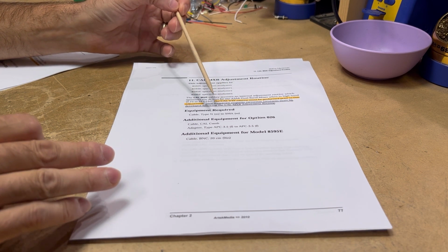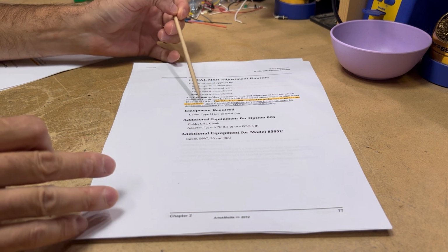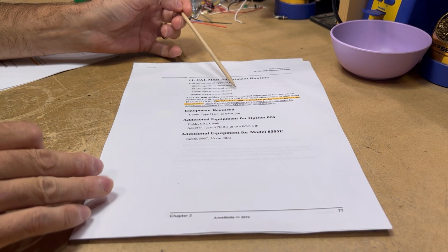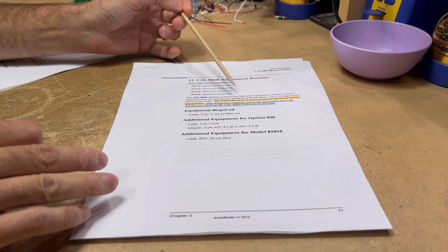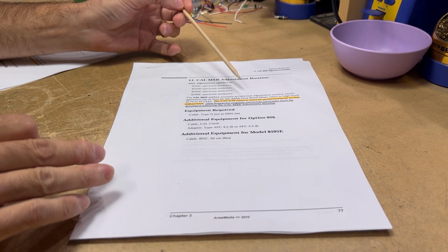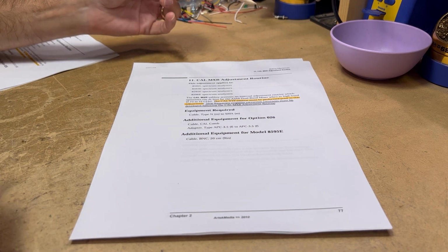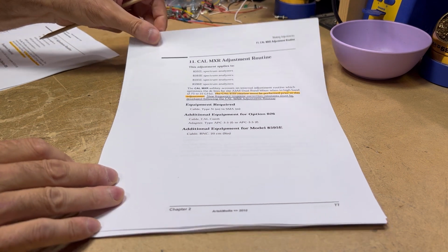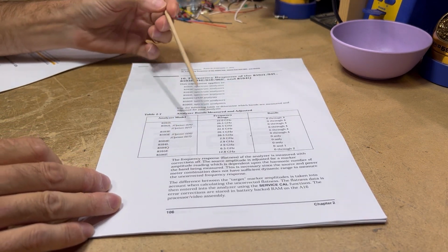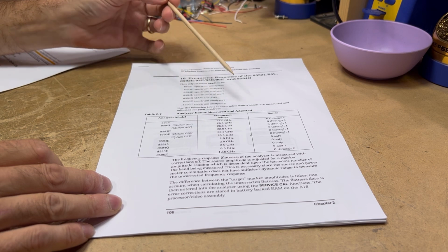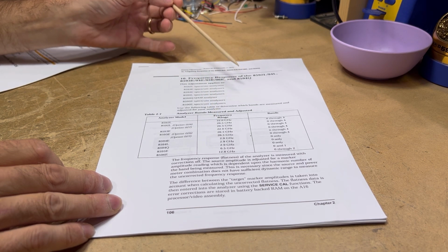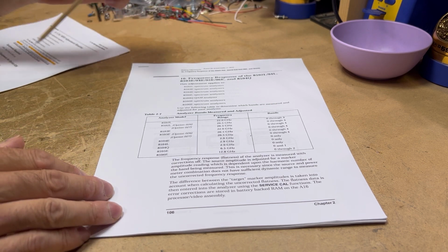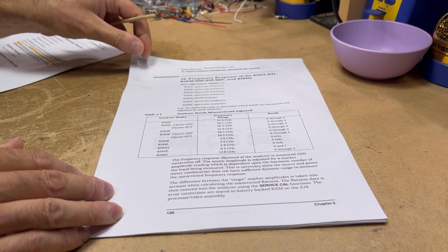So reading through this, it seemed to make sense that if we do the low band first, that's not going to be affected by the cal mixer. It looks like the cal mixer primarily is going to affect the higher bands. So we'll do the low band first, then run the cal mixer adjustment routine. And then once we complete that, we will go back to section 16 here, and we will do the frequency correction constants for band 1, which is going to be the 2.9 to 6.5 gigahertz, so the upper band of this spectrum analyzer.